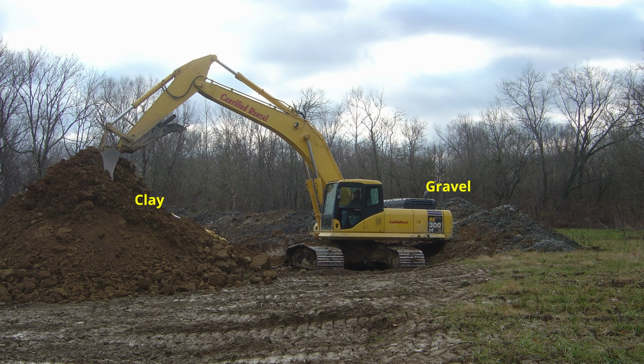The excavator is piling the silt clay texture soil being removed from digging the trench inside of the wetland being built and onto the area where the topsoil was removed. This silt clay will be later placed in the trench in layers, with each layer being compacted after the gravel is removed.